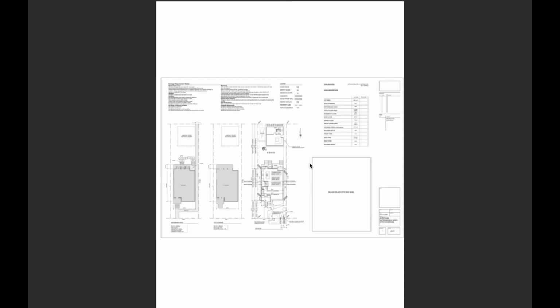So there's going to be stuff like that that doesn't jive, and the sooner that you can pick those things up, the more efficiently you can have the project go, because you'll actually start ordering different material as the things change, well in advance of, say, a beam showing up that's too deep for your architectural purposes, but it's what the structural calls for. And if you had known ahead of time, you could have reworked the design, ordered a steel beam instead, and then moved forward. So working through those kind of things is really important, but also as an apprentice, you're looking at these plans and you're starting to get an idea of what's happening with this project.